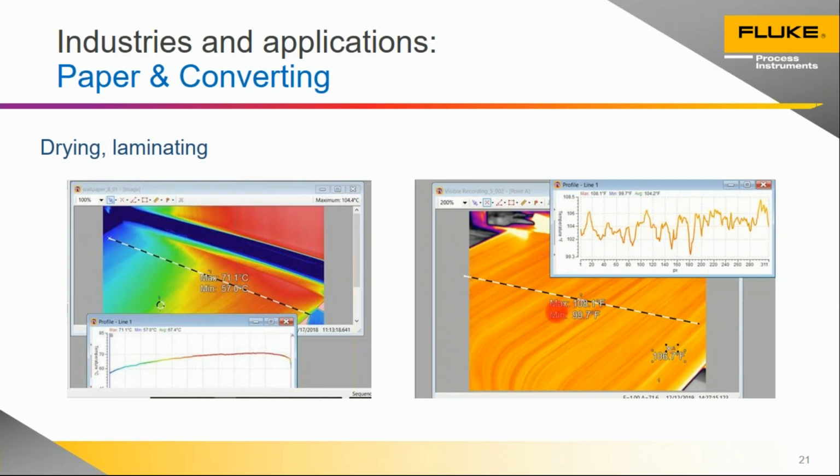What they'll do is make manual adjustments to the die bolts upstream here to maintain that and avoid having big differences from one spot to another. This particular customer uses a line scanner regularly, and we tested a thermal imager, and I believe they're going to use a thermal imager on other lines going forward, because they were able to pick out those differences even with better resolution in this case.